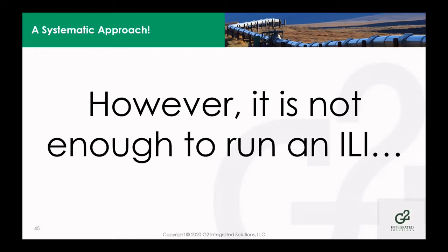At best, the comparison can only show that the inline inspection run is consistent or inconsistent with the results collected in the field. The procedure does not prove that the inline inspection meets its performance specification. The inline inspection run is accepted unless evidence to the contrary is found once the verification work has been completed, sometimes many months after the launching of the inline inspection tool, sometimes years, when it may be too late.